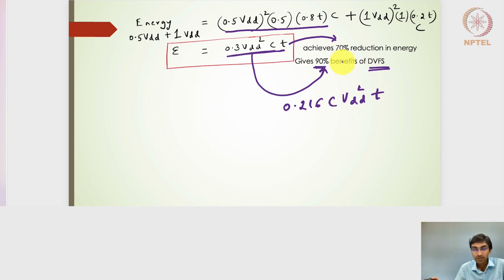So I hope you are able to understand this. I have given two examples of tiered DVFS, dynamic voltage frequency scaling, where the rate is directly proportional to the rail voltage. So if I want to configure a particular task for a particular switching rate, then I will choose that particular VDD rail, right? Now the question is, how do we choose that? As a designer, we have the ability to design particular rails.